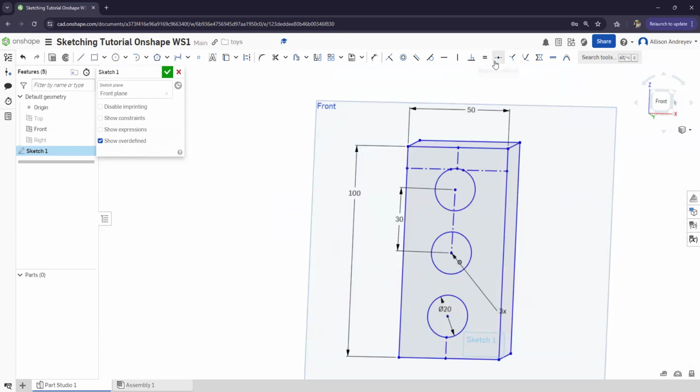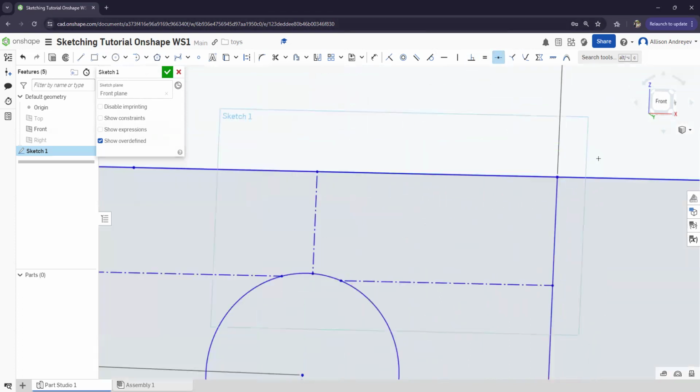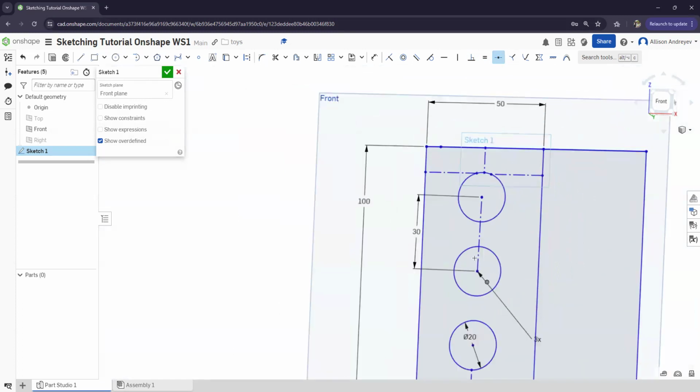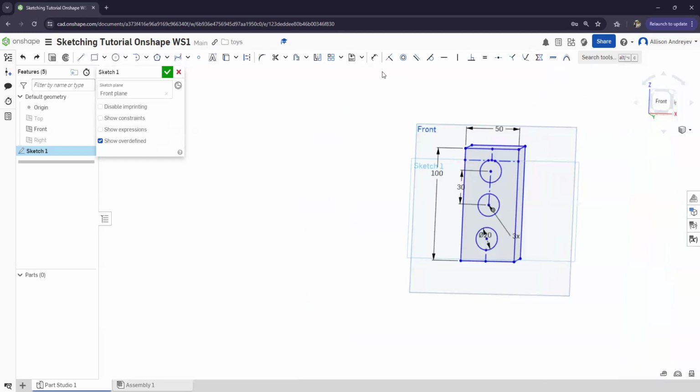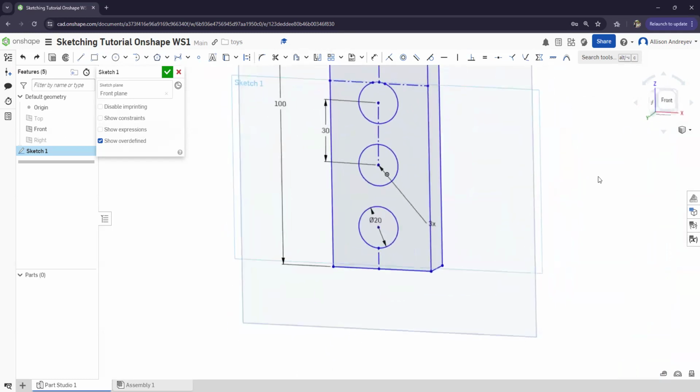And we already used the equal point, but let's say we need a midpoint. We would click on here, and then we would click on another entity, this point. And that just became the midpoint of our new line. But let's undo that because we don't really need a midpoint. And then let's see. So we have symmetric, so we can create some symmetry in our drawings. This is very similar to mirror, so it can be used interchangeably really a lot of the time. And I've already demonstrated something similar.